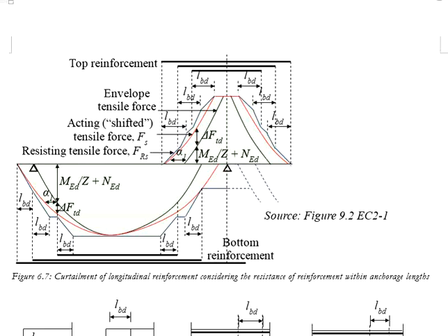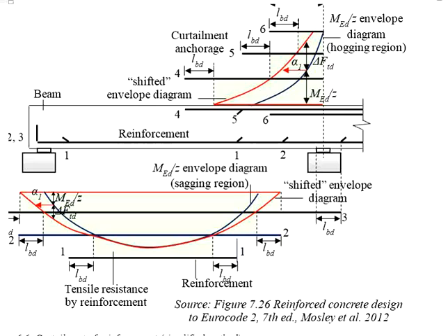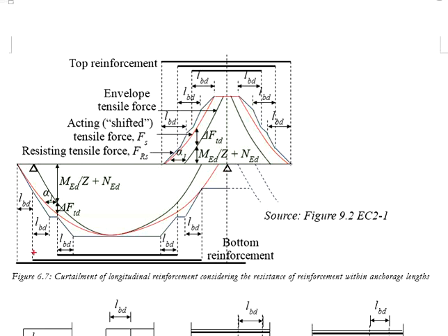However, due to practical considerations, you still need at least 2 units of reinforcement in the diameter of 12 mm to be placed on top of the beam. The purpose here is to tie the vertical shear link along the beam. And also, the number of groups of the reinforcement to be provided is often governed by the resistance that can be provided by the reinforcement.